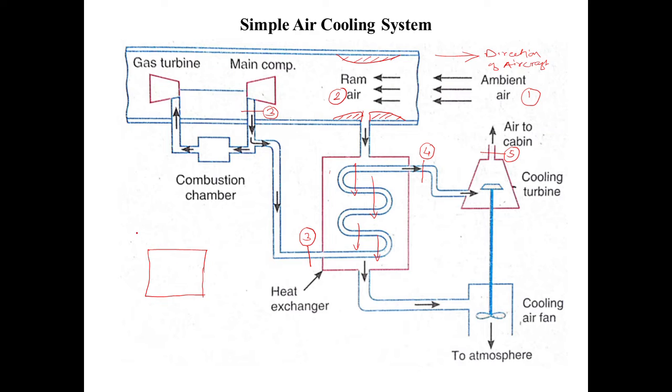Now imagine that the air is coming from the cooling turbine. So this is the cooling turbine from where the air is coming, and this is the cabin which I maintain to be cooled. Now assume that I am maintaining the temperature at 25 degrees Celsius over here, and obviously there are people sitting inside it, there are lights, so continuously there will be an increase in the heat inside the cabin. These are the factors which will be adding heat to the cabin, and it's an enclosed space, so heat can't flow outside, it will get added inside the room itself. That is because of internal factors like human beings, lights, and surrounding temperature, because of which the heat will flow inside. Likewise, there are many reasons because of which heat will go on increasing over here.